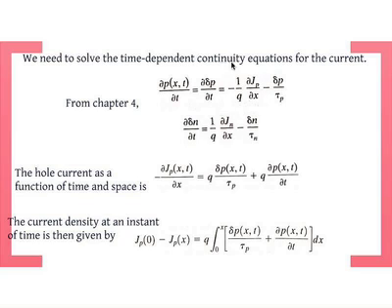This side is the carrier injection current. But this is the diffusion current. Not just the carrier injection, this is also the diffusion current. You can think of this side as a carrier injection, but we'll come back to that. This is just the diffusion current because it depends on the concentration gradient. We derived this by looking at a slab of a semiconductor with a small region where you have current coming in, current going out, and recombination happening. So go back and review that. But basically, we derived this.